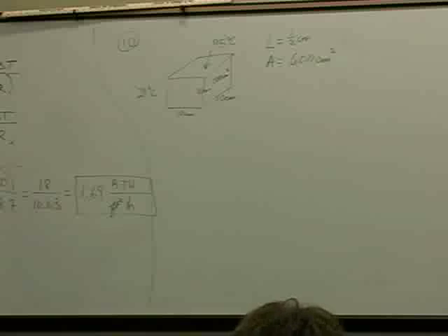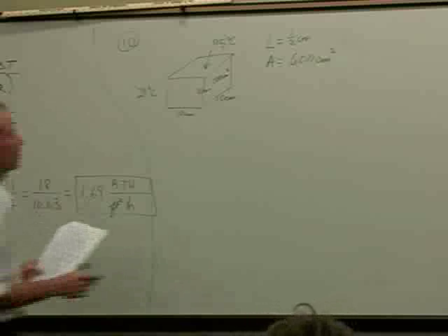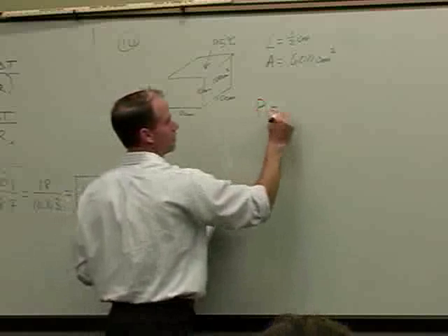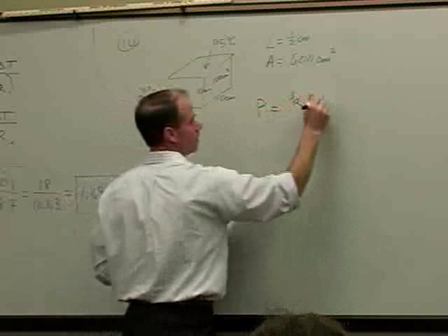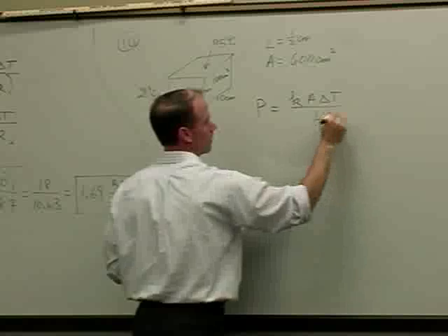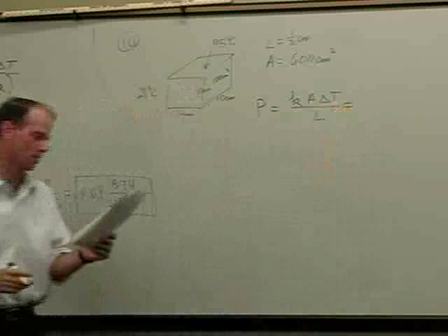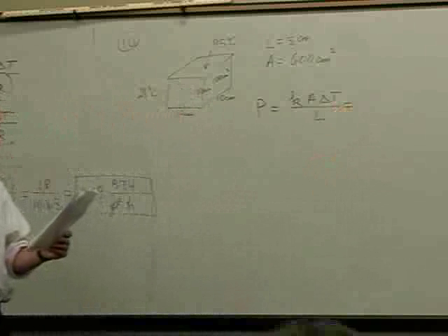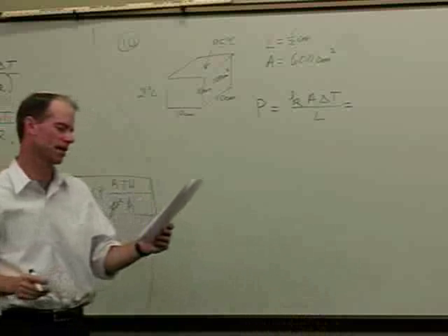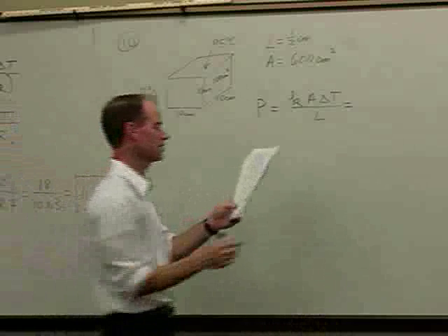Find the rate of heat loss, okay? So power will equal kAΔT over L. Thermal conductivity of the cup is 2 times 10 to the minus 4 calories per second per centimeter per degree Celsius.